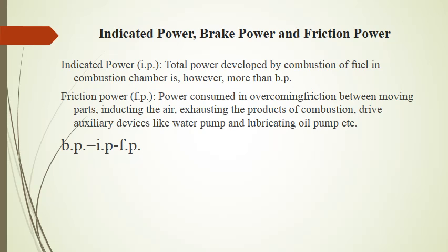The total power developed by the combustion of fuel in the combustion chamber is, however, more than the brake power and is called indicated power. Out of the power developed by the engine, that is indicated power, some is consumed in overcoming friction between moving parts, some in the process of inducting the air and exhausting the products of combustion from the engine combustion chamber.